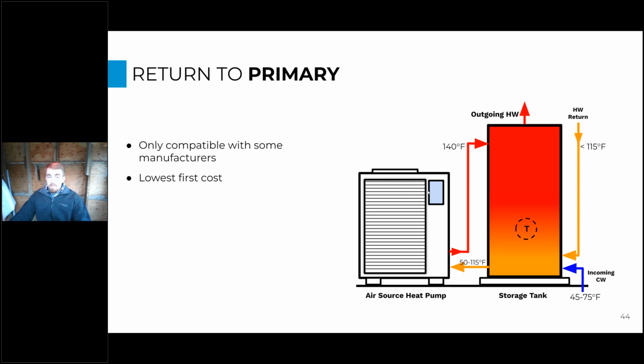On the other hand, you do have to increase the size of your primary heat pump water heater because you have a larger load to satisfy with that primary heater. But in hospitals, if we're talking about requiring a redundant heater for every system, then we just require that redundancy for the primary heater rather than requiring a redundant temperature maintenance storage tank and redundant temperature maintenance heater.